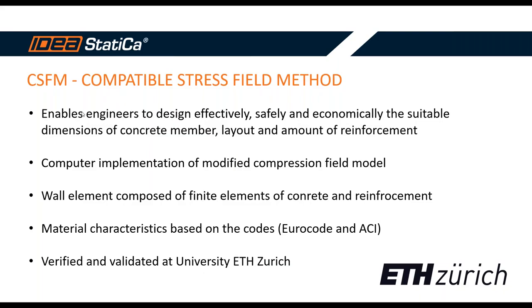This method enables engineers to design effectively, safely, and economically the suitable dimensions of a concrete member, layout, and amount of reinforcement. From the physics point of view, it is actually an implementation of the modified compression field model, and the analysis is based on finite elements. There are separate finite elements for concrete and reinforcement.